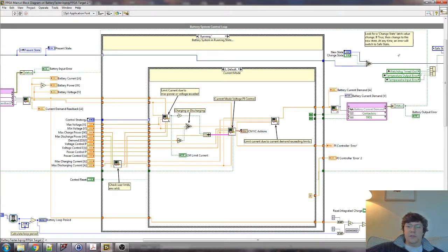The usual limit at that time was that it was okay if the total full capacity at any time was at least 80% of the capacity when the battery was new. After that it was deemed to have failed effectively, even though it still worked fine, just not with the same capacity. You'd put it into some second life application like a storage setup, or you could probably reuse it as a GSM base station UPS or something like that. A lot of lead batteries are found in the mobile phone network.